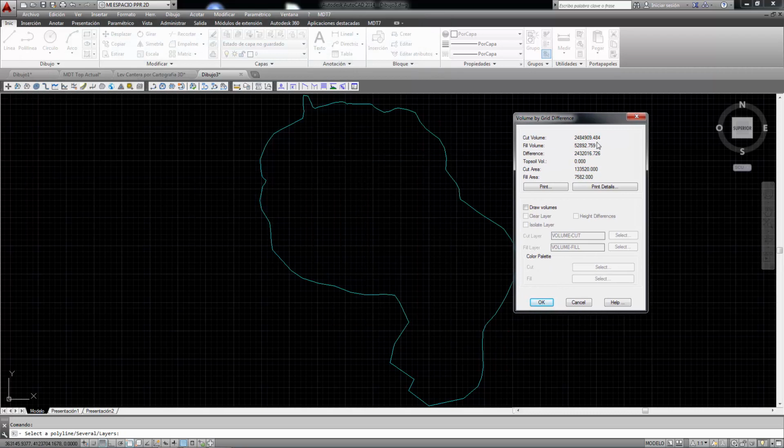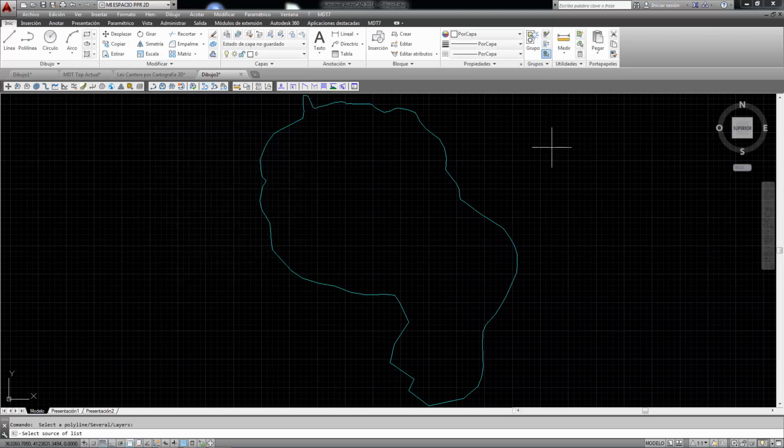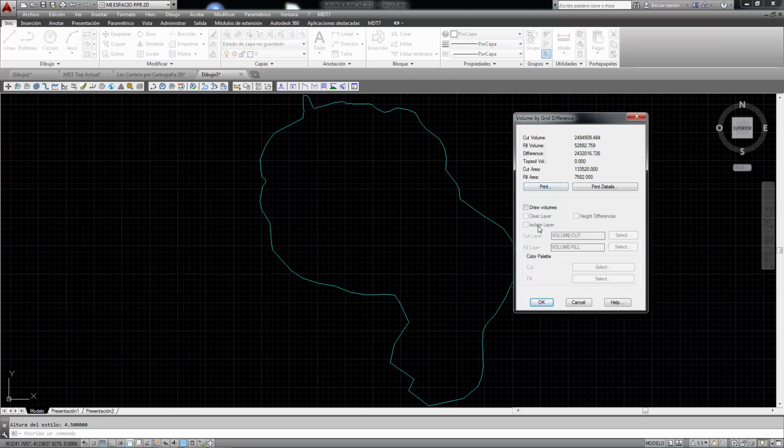We can also use a contour or line to define the area whose volume we wish to calculate, as in this example, or even a height filter, a limit between which we are going to calculate the volume between a minimum and maximum height. We choose our basic map as the first file and the more up-to-date file as the second.